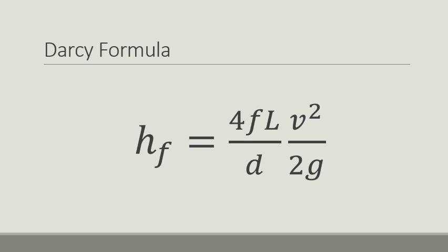It is known as the Darcy formula for the loss of air in pipelines. Although the frictional resistance is only proportional to V square for turbulent flow, the formula can be applied to viscous flow, in which resistance is directly proportional to V, by making F inversely proportional to V. So there are other expressions of the Darcy formula, which one of them can be proven thus.